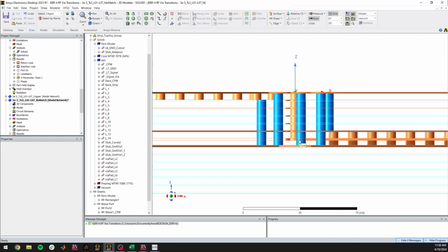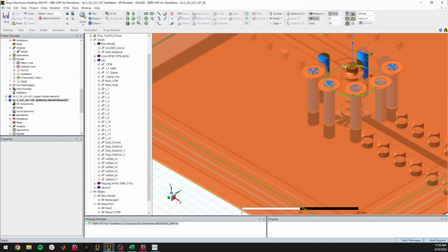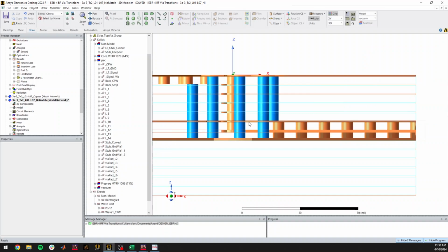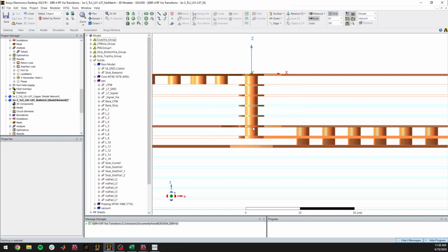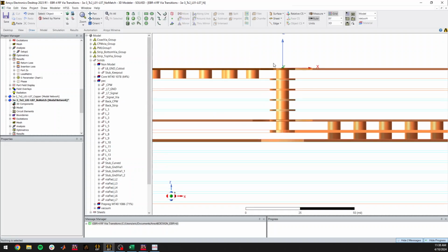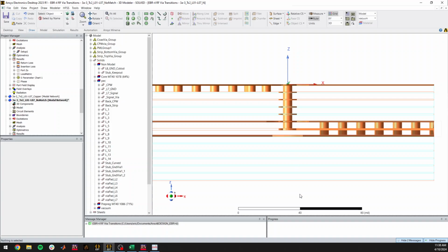If you're not able to use this, you're probably going to be using a through via or something similar, and there's a technology called back drills. And let me just get rid of this for a second. With a back drill, that essentially could be a through via or another type of buried via, where there's a physical drill that comes up from the bottom, drills out part of that stub, and leaves you with a structure that looks similar, but there may be a little tail or stub on the bottom of your transition.